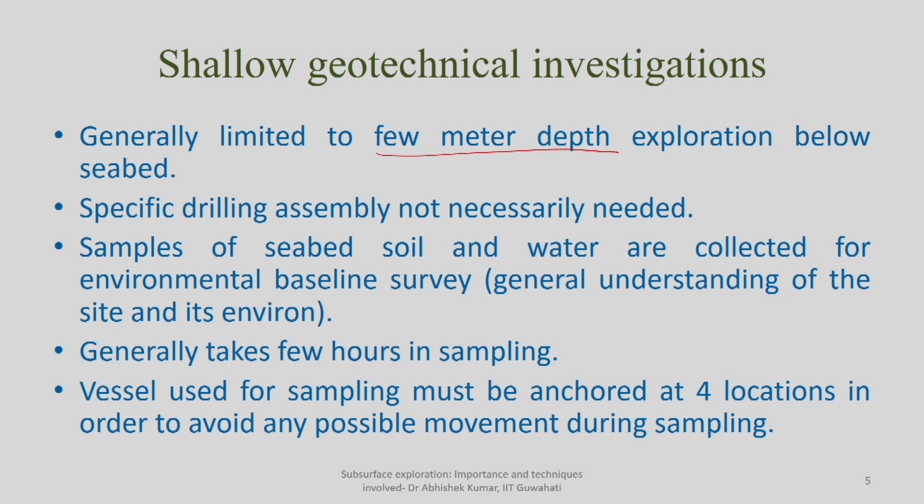You cannot go for 50 meters or 80 meters based on shallow geotechnical investigation, because the objective here is just to know what kind of soil, what kind of strength characteristics, or maybe in terms of chemical composition, what kind of medium characteristics are available at shallower depth below the seabed.